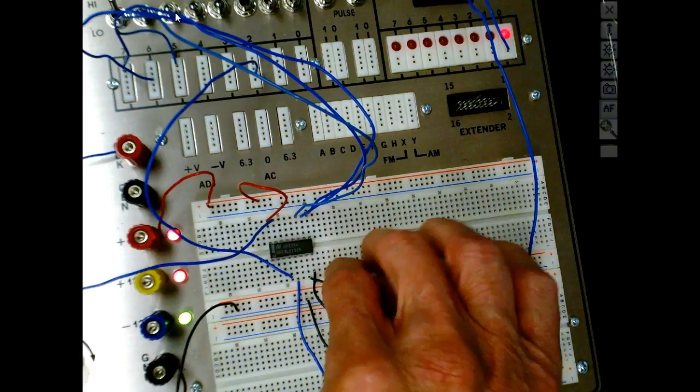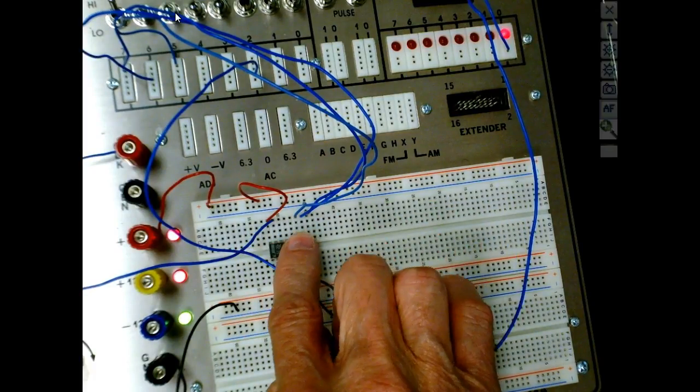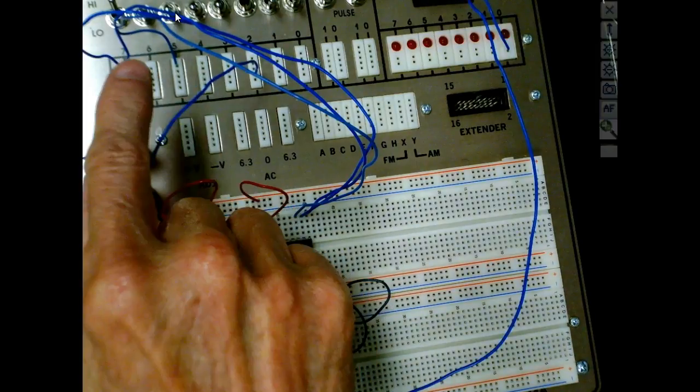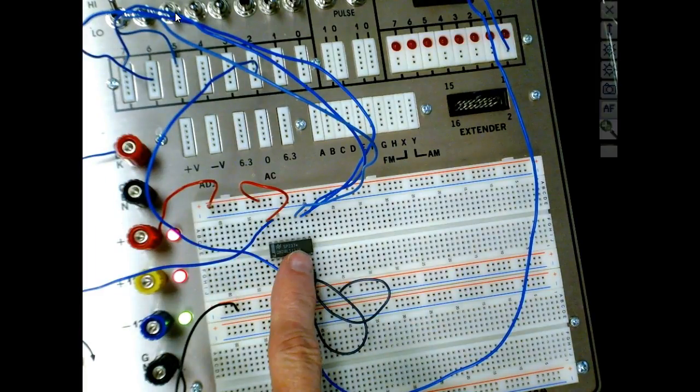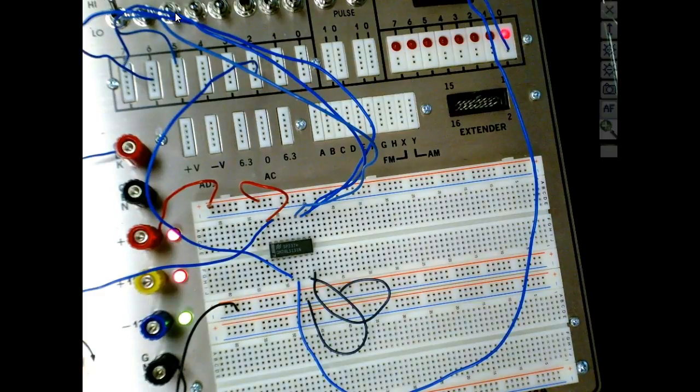So what we could have is I could have 8 inputs over here, and I can select which input is passed through to the output by the select input. So basically we're doing what? We're electronically moving that switch. So I'm letting 8 inputs share 1 output, but not at the same time. So what is this? Is this broadband, or is this frequency domain, or is it time domain? It's time domain because I'm switching one at a time.